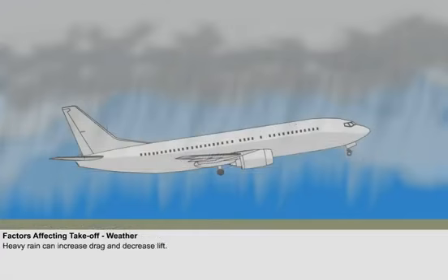It may seem strange, but excess water on the aeroplane can lead to the same effects that ice has. In heavy rain, research has shown that lift can be reduced by as much as 30%, and drag increased by as much as 25%. This, combined with increased aircraft weight, can create a significant performance loss, and thus takeoff in heavy rain really should be avoided. Unfortunately, this advice is too often ignored.